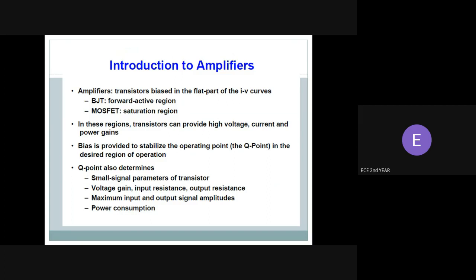As the bipolar transistor is a three-terminal device, there are basically three possible ways to connect it within an electronic circuit, with one terminal being common to both input and output signal. Each method of connection responds differently to the input signal within a circuit, and the static characteristics of the transistor vary with each circuit arrangement. Common base configuration has voltage gain but no current gain. Common emitter configuration has both current and voltage gain. Common collector configuration has current gain but no voltage gain.